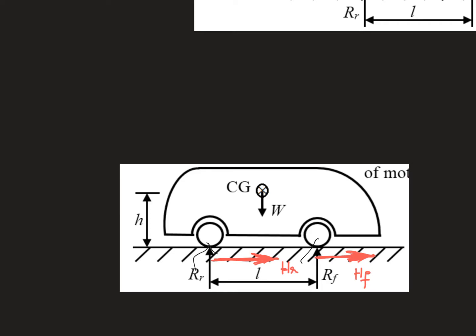as shown over here. So now we have two forces here, capital R and HR. HR is the horizontal force that is acting on the car, which causes the car to move forward actually. Same thing for the front wheel as well. Now altogether we have around 5 forces acting on the system, isn't it? I think I got my numbers correct. So 2 over here, 2 over here, and the 1 force over here. So this is the free body diagram.